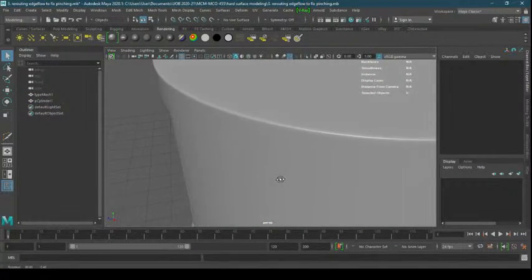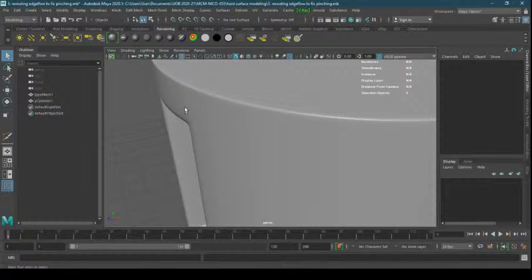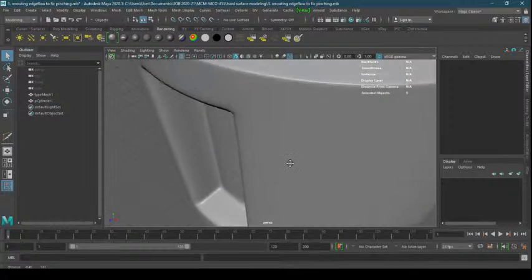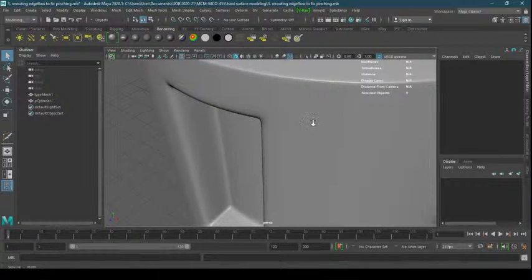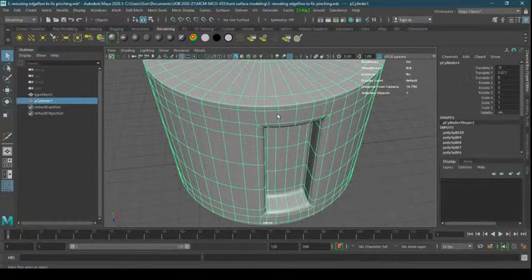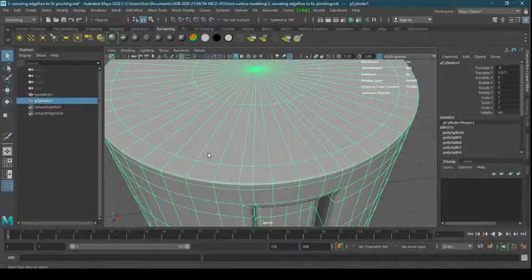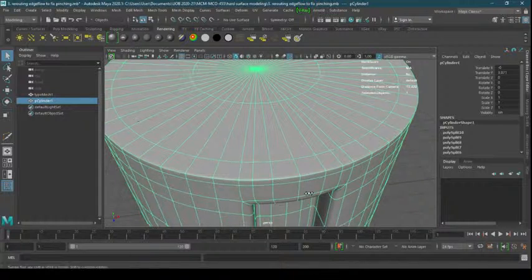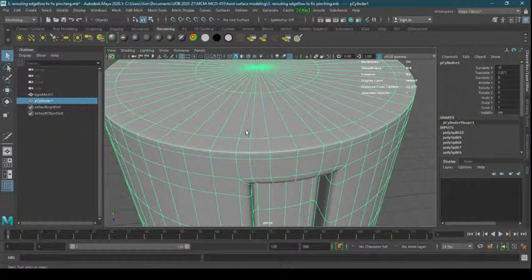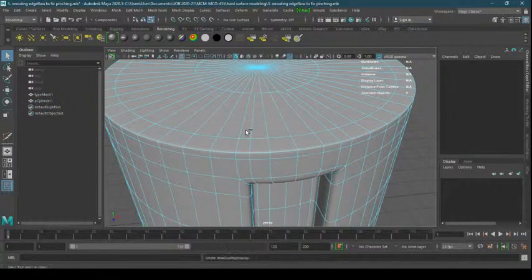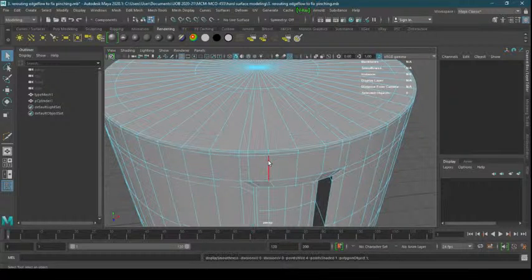If you notice, pinching is still there. A little bit it fixed. It's not harsh like before, but still it is there. The reason is that look at these gaps. These are very wide gaps, but here the gap is very narrow. This narrow gap is already causing a pinching. So we have to fix that by rerouting, not by this method. So now I will go back to 1.